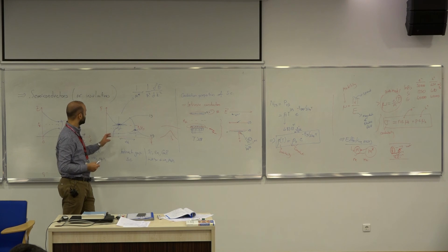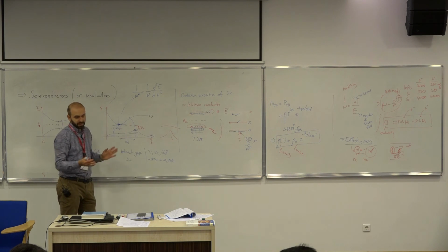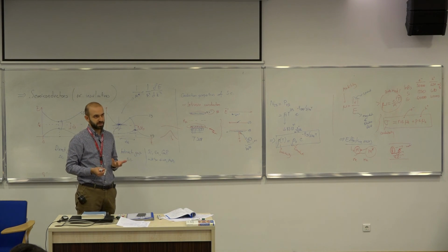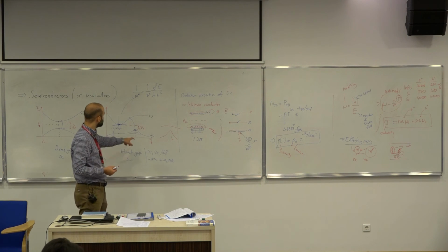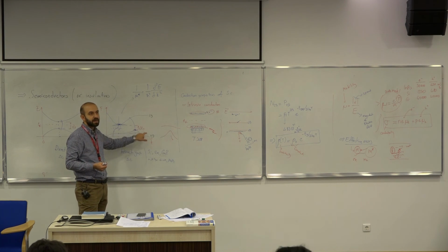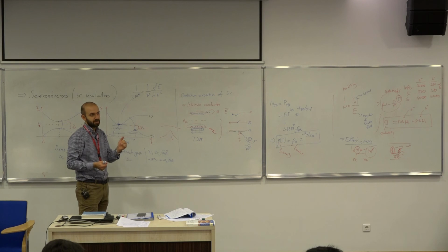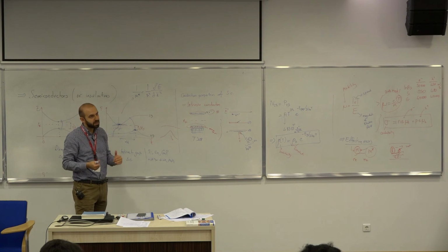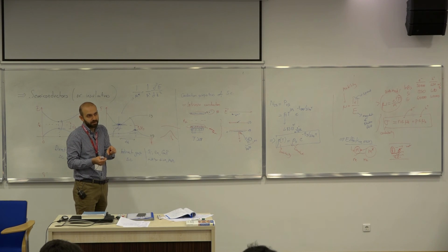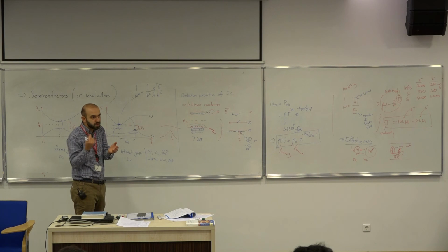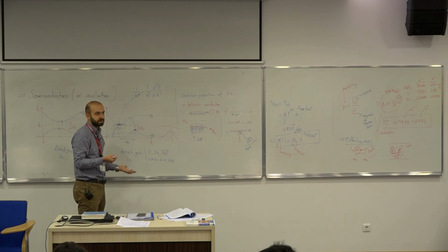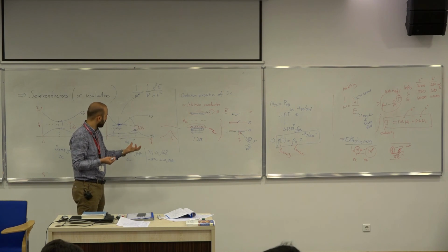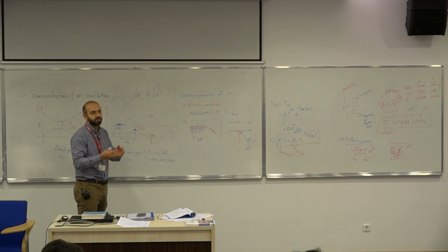If you look at silicon, for instance, there is no single valence band. There are multiple bands, called light hole bands, heavy hole bands, and then there is spin orbit splitting, where the spin interacts with the orbital angular momentum, so there is another band.